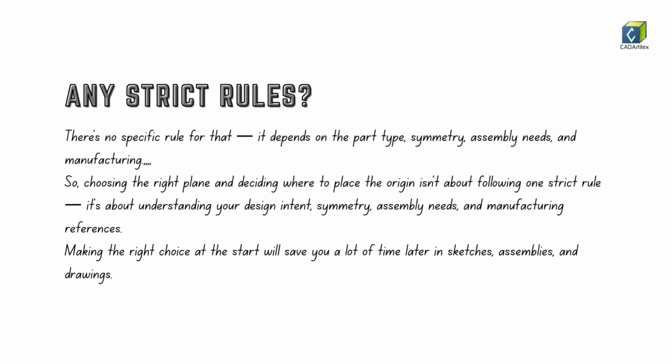It depends on the part type, symmetry, assembly needs, and manufacturing needs. So choosing the right plane and deciding where to place the origin isn't about following a strict rule. It's about understanding your design intent, symmetry, assembly needs, and manufacturing reference. Making the right choice at the start will save you a lot of time later in sketches, assemblies, and drawings.